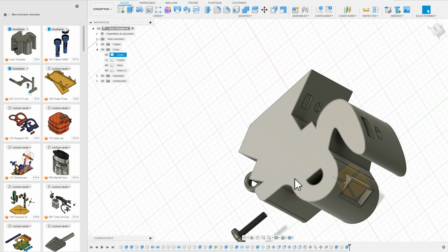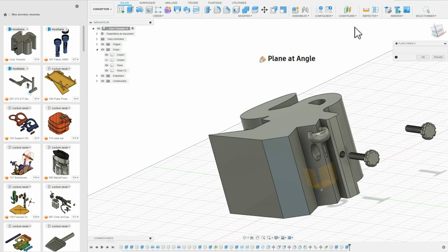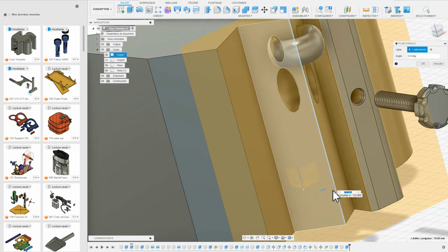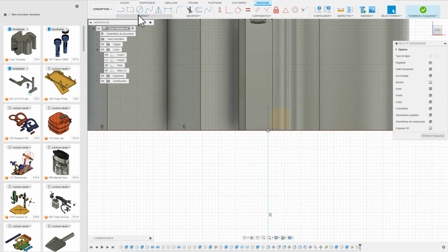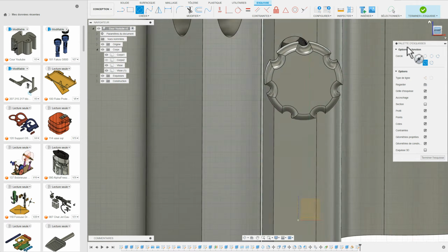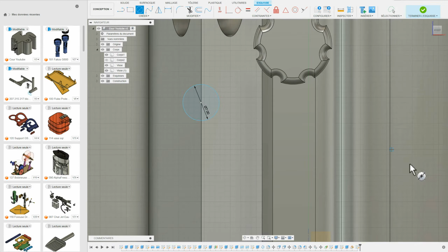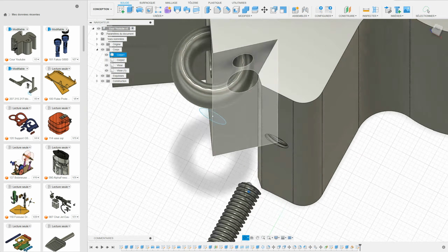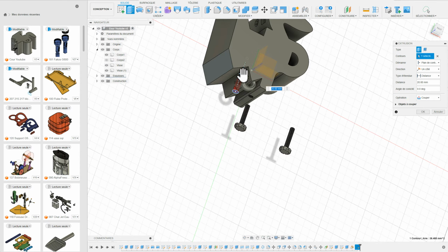We've just seen the tangent plane, now we'll look at the angled plane. I move the part again to find some angles. I go to Construct and choose Angled Plane. We see several angles here, but I'll take this one. I select it, enlarge, and click on the sketch to start drawing. Again, I select the circle. I look for a working position. I'll start the circle here and give it a dimension of 7. Note, I always use round dimensions, but I could have set it to 7.32 for example. I reposition the part a bit more and here again, we'll extrude it inward.